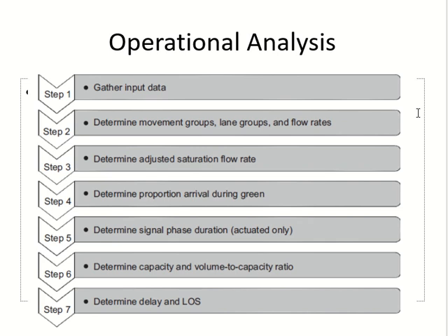After design, you check, am I getting level of service C or better or worse? If you are getting worse, then you can change your design. This is how we can use the level of service concept for design. Once you know how to find out the level of service, you can use it for design.